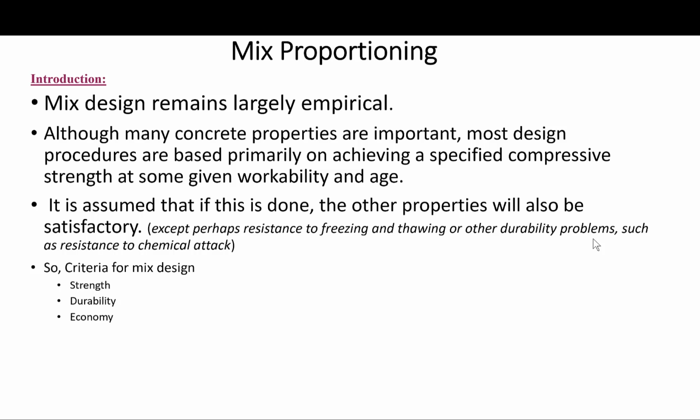And although many concrete properties are important, most design procedures are based primarily on achieving a specified compressive strength at some given workability and age.